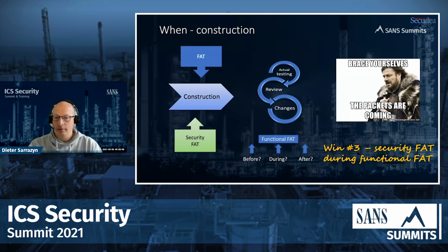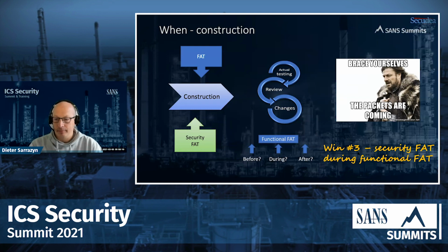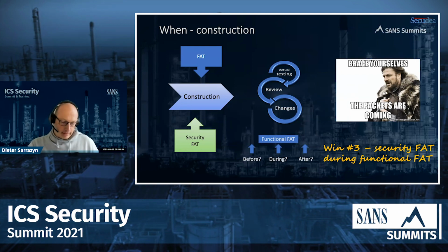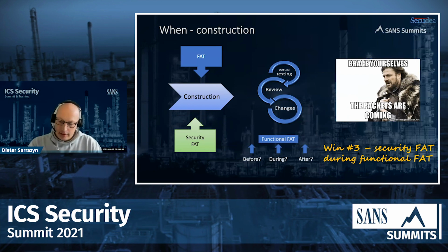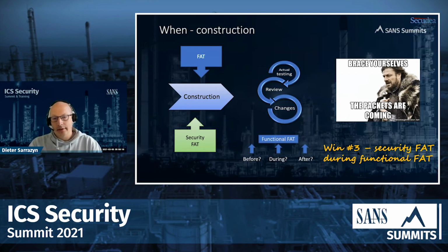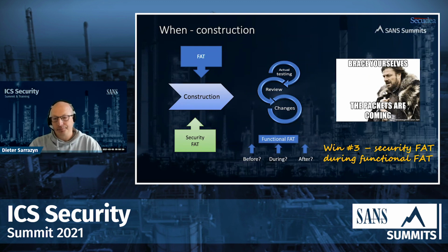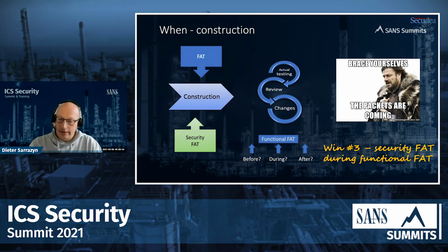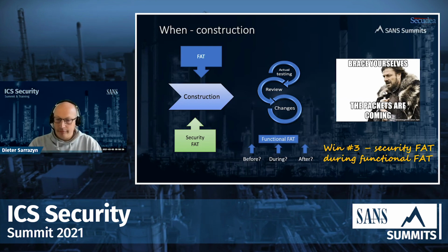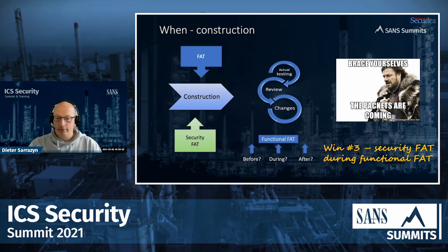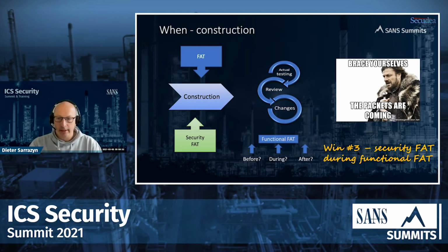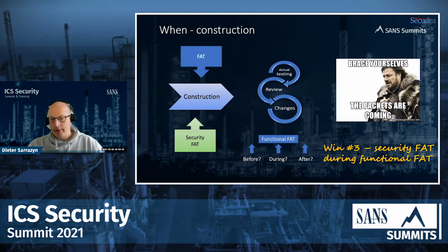system towards security testing. To give you an example of a security FAT testing I did back at Siemens, I think it was a T3000 DCS environment. We were doing security testing and they were fully busy with doing the functional testing. And suddenly one of the engineers yelled out, "Hey, stop, this is not working anymore. What are you doing?" I said, "I'm just doing port scans." "Oh, we lost that PLC."